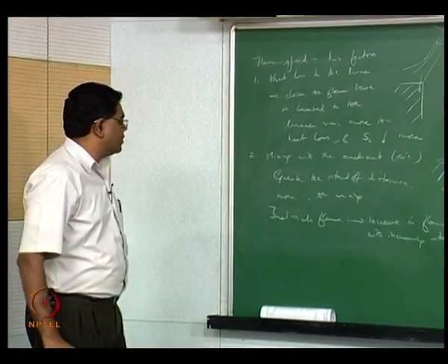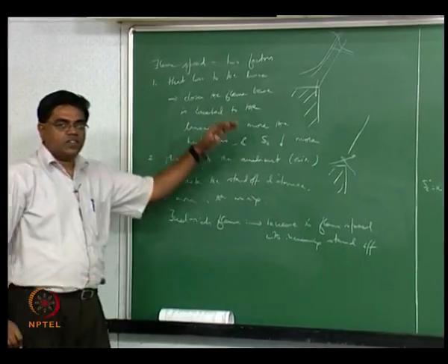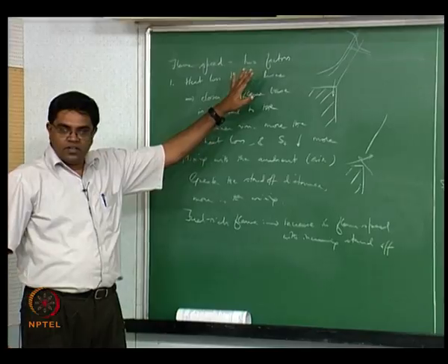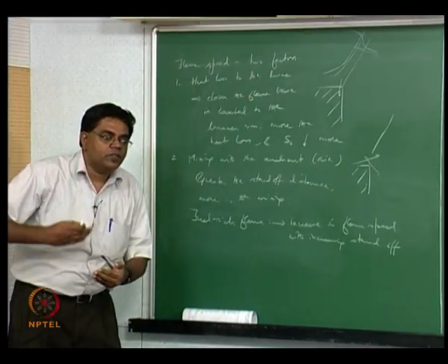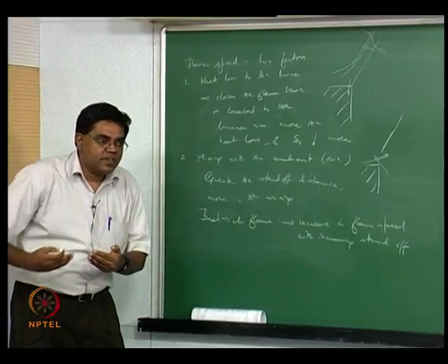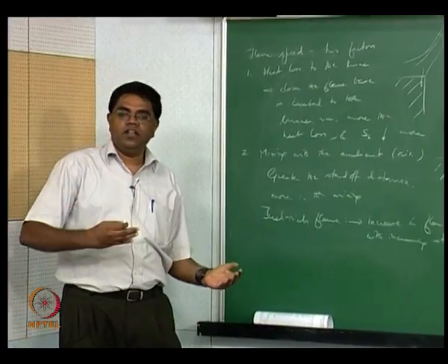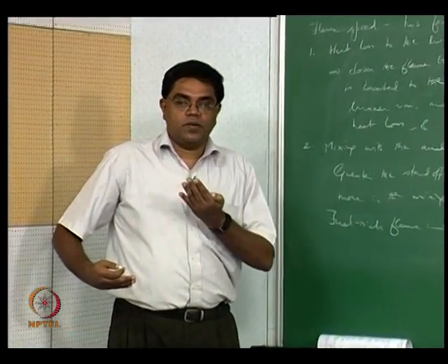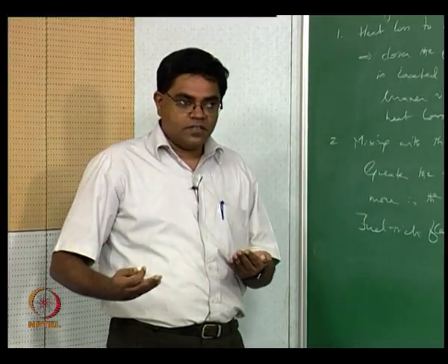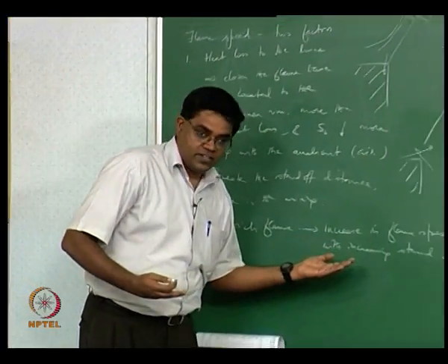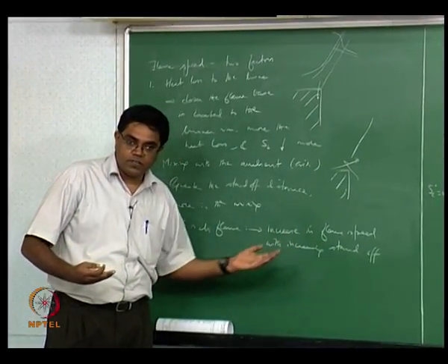Right, and this goes in the same direction as what the heat loss effect was. In the case of the heat loss, what we understood was the closer the flame is to the burner, the lesser is its flame speed, or conversely, the farther it is from the burner, it's going to have a higher flame speed because of less heat loss. This is exactly what we are saying here. Increase in the flame standoff means an increase in the flame speed because it's fuel rich.